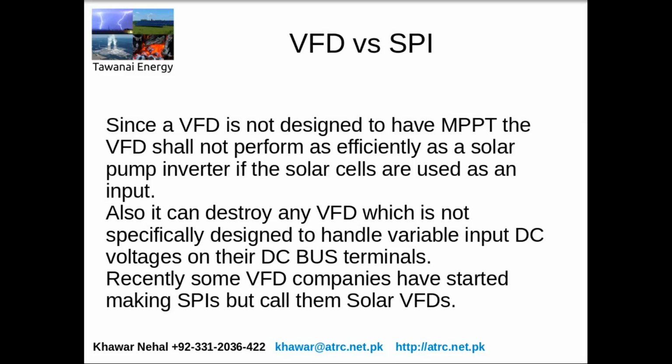Since a VFD is not designed to have MPPT, even if you do somehow get the VFD running on a solar panel, you will get less efficiency, and secondly, you run the risk of destroying a VFD designed for AC input and not for solar panel input.